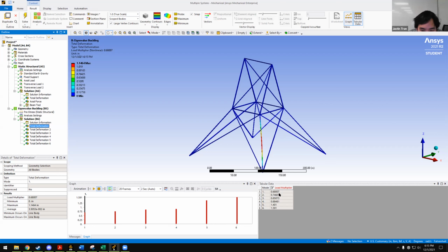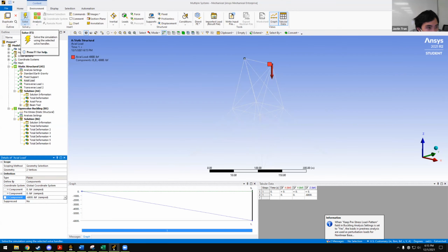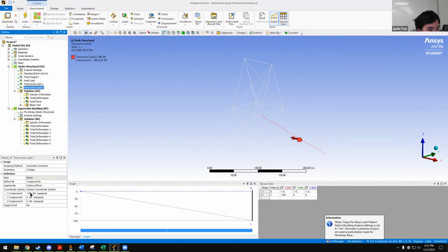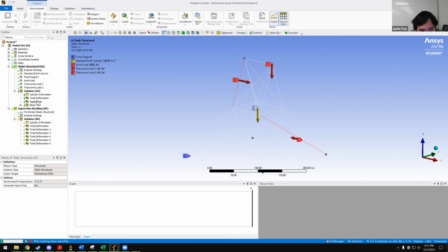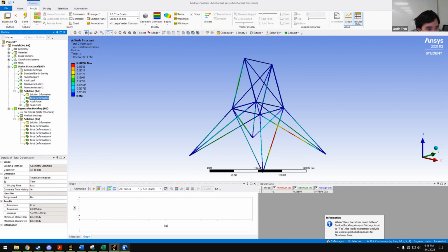Yeah. And so you're going to take that multiplier, and then you're going to multiply that by all the different mode values. And so if you go to Axial Mode, you're going to multiply that minus 10,000 by 0.68. And so it'll be minus 6,800. And you're going to do the same for the transverse modes as well. Yeah, so it has to be for all the modes. Yeah. And so what this is basically saying is that you actually reach buckling before the structure would buckle kind of before all that stuff. Yeah. So this would be the first point of buckling for you.